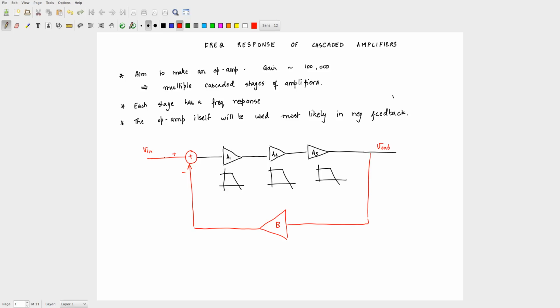There is no speciality. See, it will be the same. It's just that when I draw A, I'm visualizing an amplifier. The unit B itself, as we'll see on the next slide, is typically some kind of passive element. It's not an active element, the feedback block, most likely. The forward elements are all gain stages. For our purpose, the return stage is, for example, an R1, R2 or an R1, C1 kind of combination. So that's why you can draw it in any way, there's really no problem.